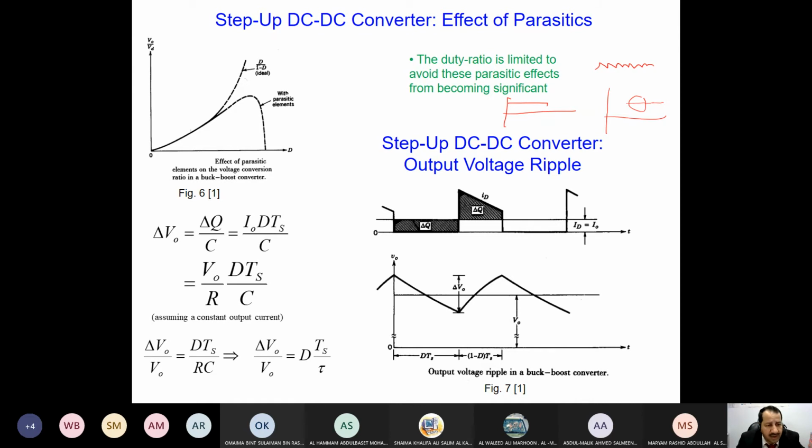Now, if I sketch the diode current of the circuit, you remember we said at the beginning, the switch is conducting, the diode will be open circuit, so zero current will flow. And when the switch is open circuit, the diode will conduct. It will conduct the inductance current, and then we can see it decrease. The inductance current is going to decrease. Now this is IO, which separates these two areas, which represent the charge we store and release in the inductance.